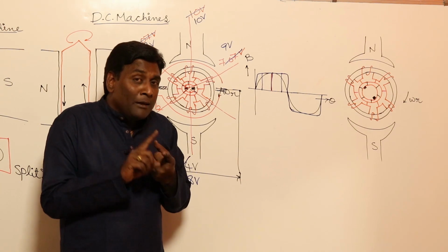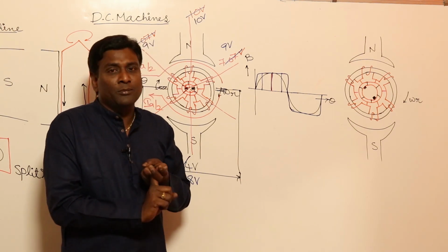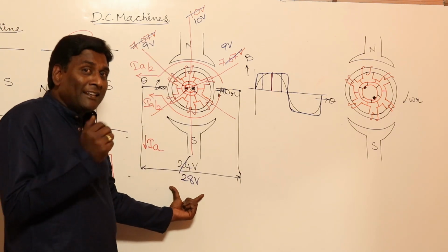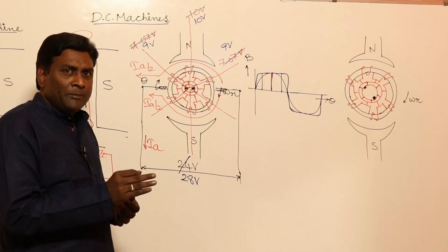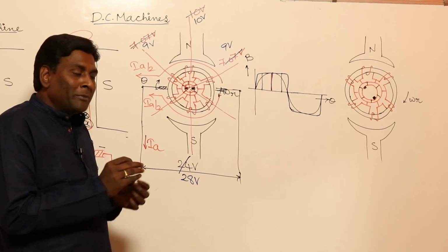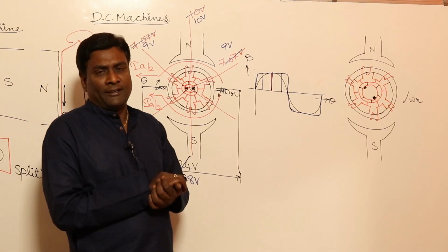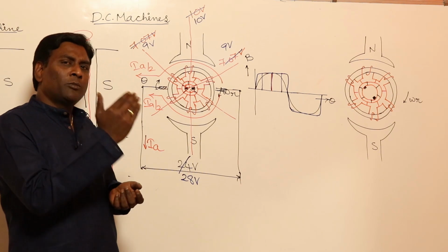Yes. So for the same magnitude of insulation, for the same stress upon insulation, output voltage is going to be increased or not? So the conclusion is very simple. In my DC machine, the flux density waveform is intentionally made flat topped. How to make it flat topped, we will see later.